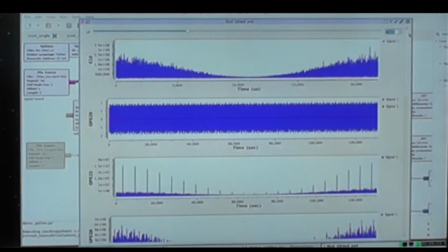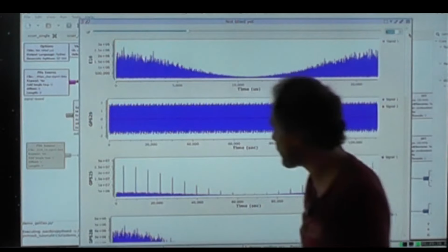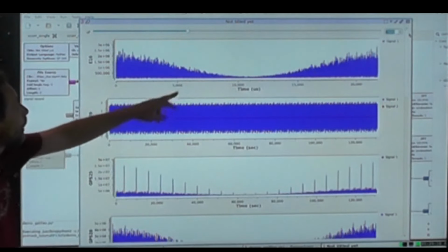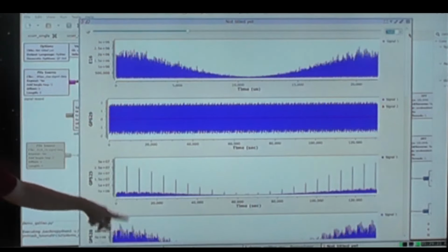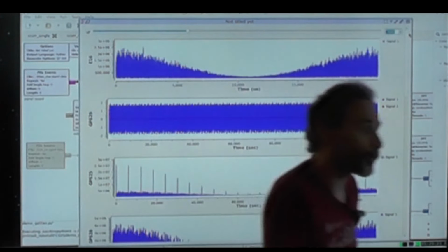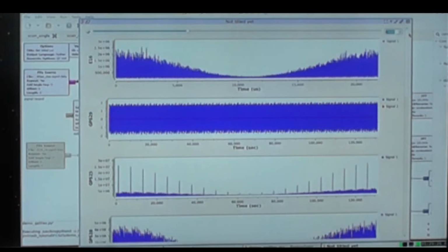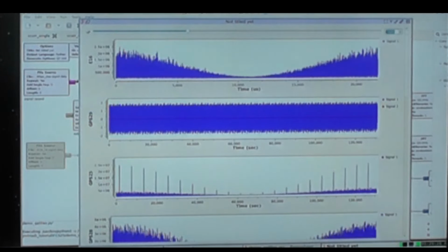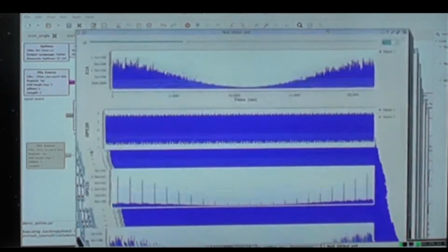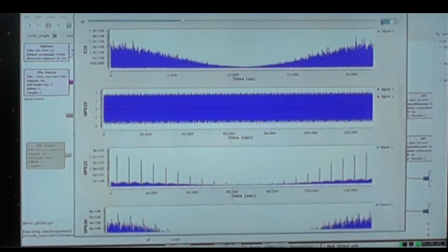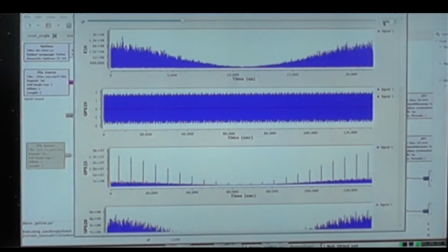Yes, there is a bit of lag because my computer is overloaded, but you see that now I shifted to 3.6 kilohertz, and you see GPS 25 correlating, and of course GPS 28 and 29 no longer correlate. And finally, if you want to see the Galileo satellite, I will leave it as an exercise for home to understand how the Galileo signal is working.